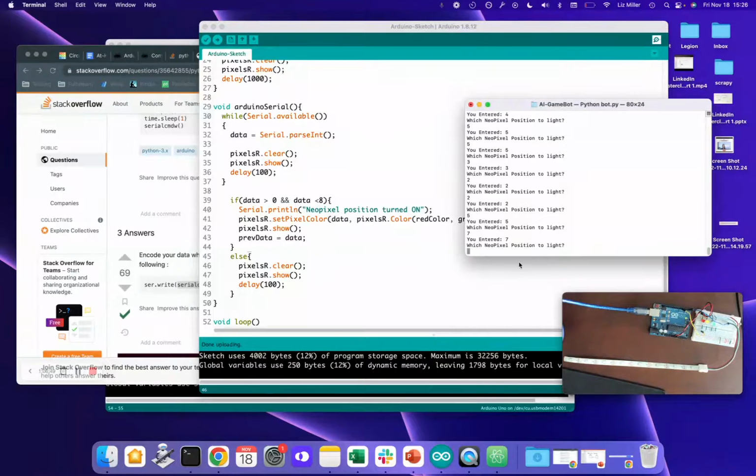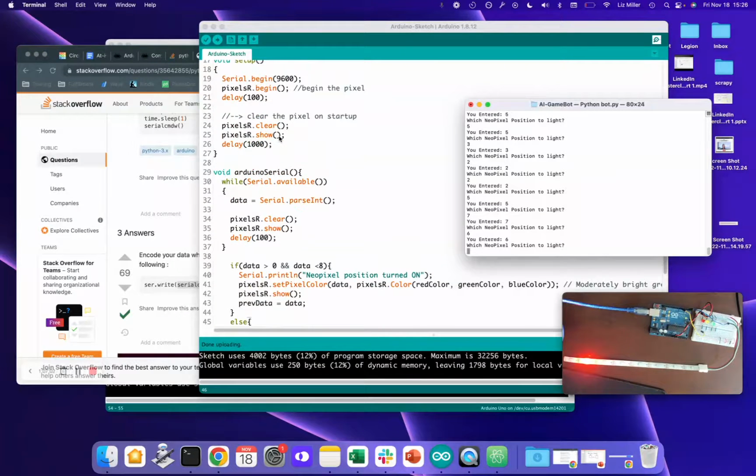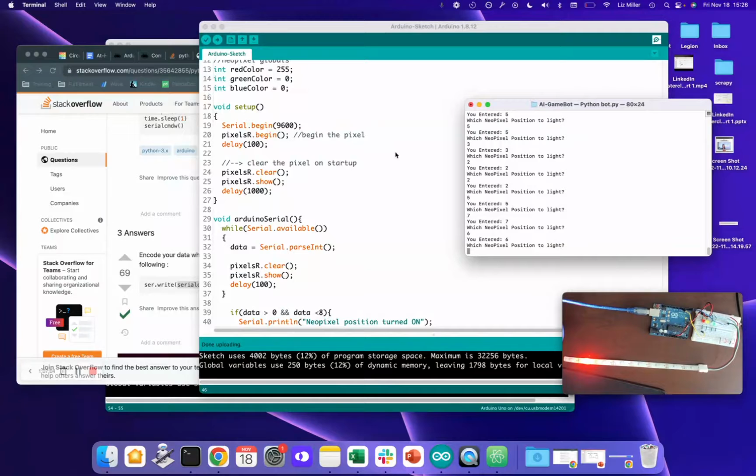And then if we go in here and we run it, this again is just sending data from the serial monitor to this NeoPixel LED. I have the color set to red. This is RGB, we can change the color, but I just figured we'd take a really obvious color to use. So now if we type in, let's say 9, I'm hoping that everything shuts off. Yep. Okay, cool. Because there is no index 9. If we index 0, we should be this guy. Let's see what happened.